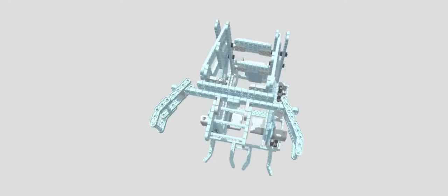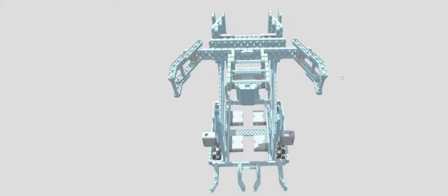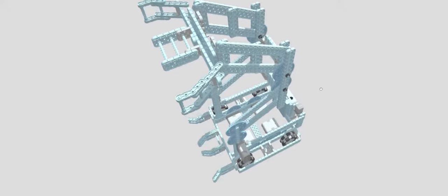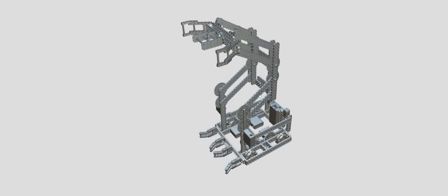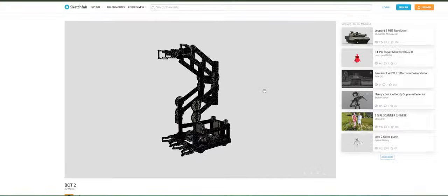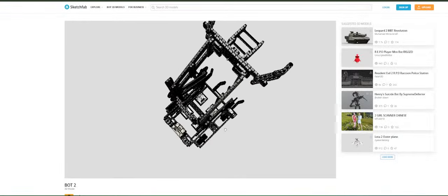So how would you change the claw to make it actually work for beams? Like I was saying, I'd add a cascade at the back. Maybe turn the double reverse 4-bar into a cascade as well, so it'll have 2 cascades. Or I was thinking, there's this structure in the middle to grab it. I can maybe add pneumatics on it, so it pulls it backwards and increases the space. So I'd be able to get the beams, and then the pneumatics goes forward, adding the structure in the middle, so I can pick up 2 pins at a time. That's very original and very smart. So congrats on winning second place.